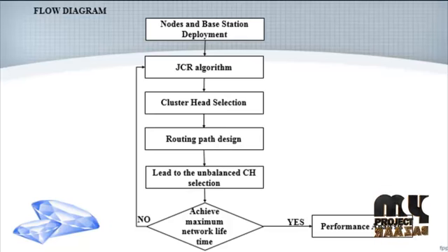The connectivity problem discussed in this paper focuses on the connectivity among the cluster heads. Every node has a maximum transmission range denoted by Rmax. This motivates the requirement of keeping network connectivity within the limitation of Rmax. The critical transmission range, that is the CTR, is less than Rmax. The CTR is defined as the length of the longest edge of the Euclidean minimum spanning tree built on the nodes. If this assumption is not satisfied, the network will be disconnected even if every node is selected as cluster head and uses its maximum radio power for data transmission. This assumption can be satisfied by reasonable node deployments.